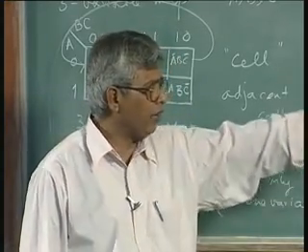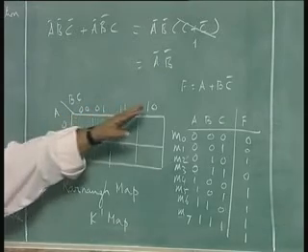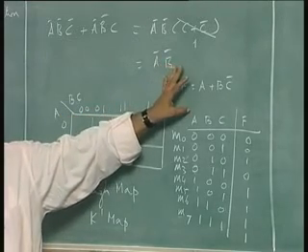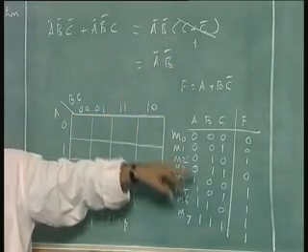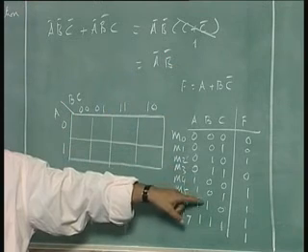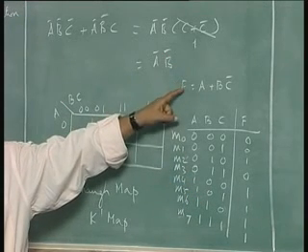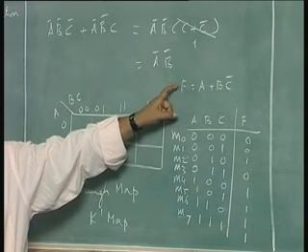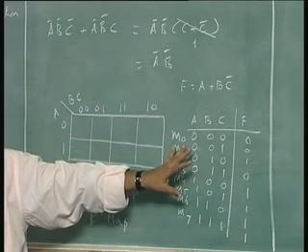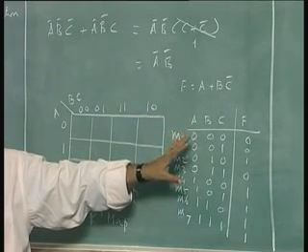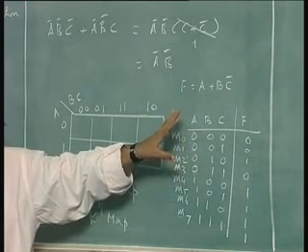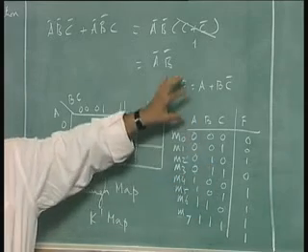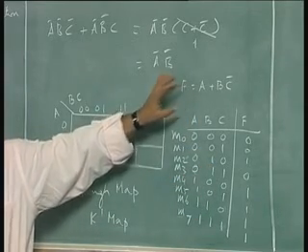So I don't even have to write this truth table. Of course, this one is what you should get finally. This is what we started with. But this is the truth table which we considered and said that this is same as this. We first did a circuit for this. Then we said the circuit represents a truth table of this type. And then we proved yesterday using Boolean algebra that this table can be represented by this function.